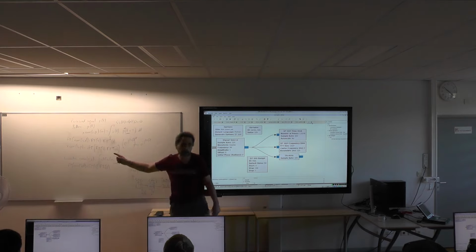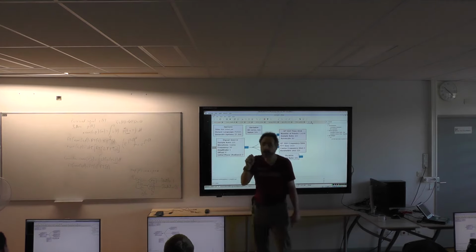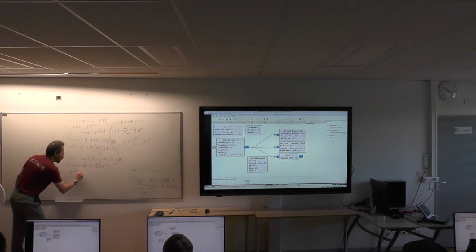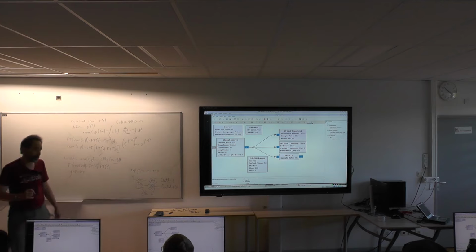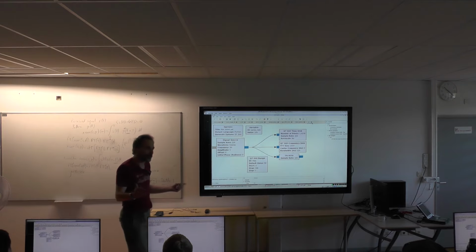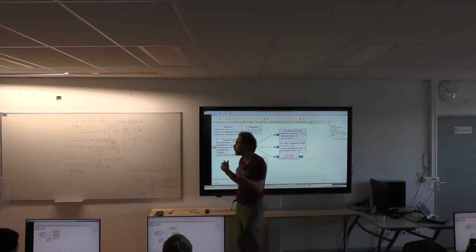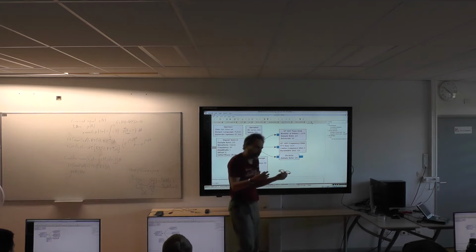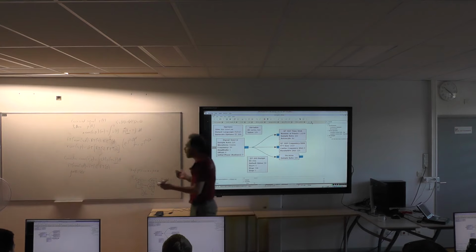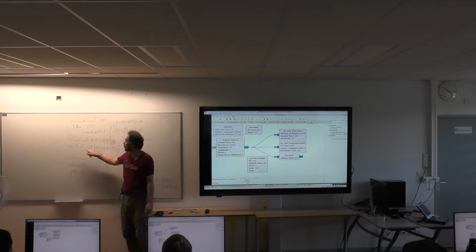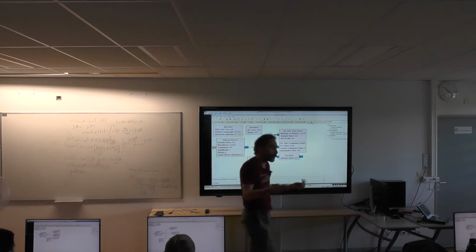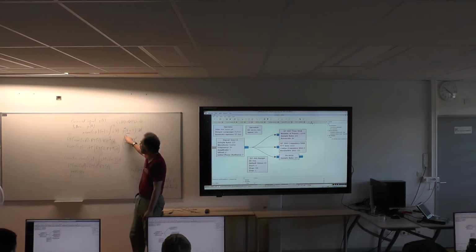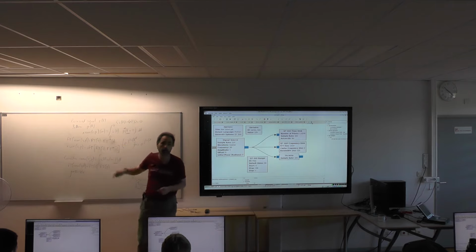But the reason why I'm emphasizing this is if you read GNSS decoding software, and the best one you can read is GNSS-SDR from Carles Fernandez and his team at the Technical University in Barcelona, you'll see many, many Fourier transforms everywhere. And if you have not realized that you're computing the correlation in the Fourier domain, you wonder why we have all these Fourier transforms everywhere in the SDR processing of GNSS signals. And that's the reason. It's much more efficient to express the cross correlation in the Fourier domain because you have an n log n algorithm in the fast Fourier transform rather than the n squared complexity algorithm, because you have n multiplications that you must repeat for the n possible values of tau, the n values of a delay. Okay.